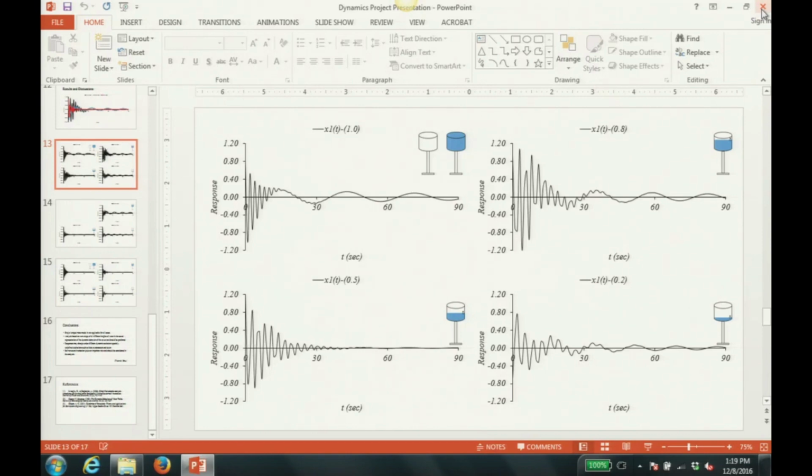In a way, it says that when the water starts sloshing, it helps in the damping, because we assume 5% for all of them, but as you can see, this one by 30 seconds is still the same behavior, but this one by 30 seconds is almost dying out.